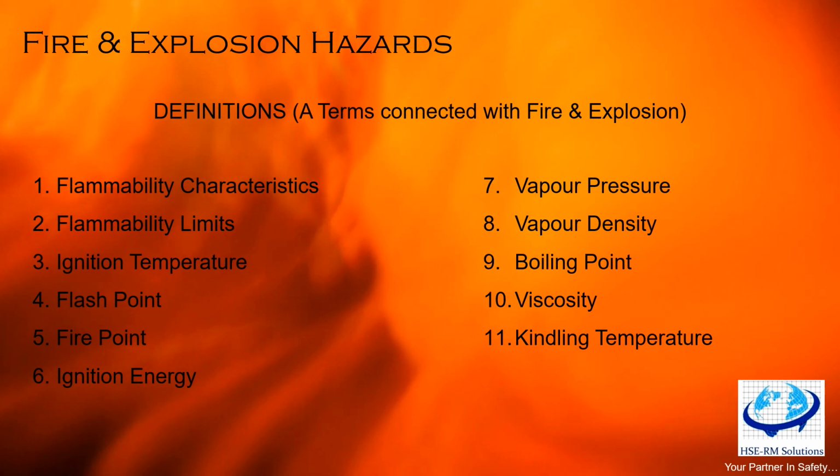So how much percentage of gas is present in the air decides whether it will be explosive, whether it will burn or not. Below the lower limit, the mixture is too lean to burn, so it will not burn.